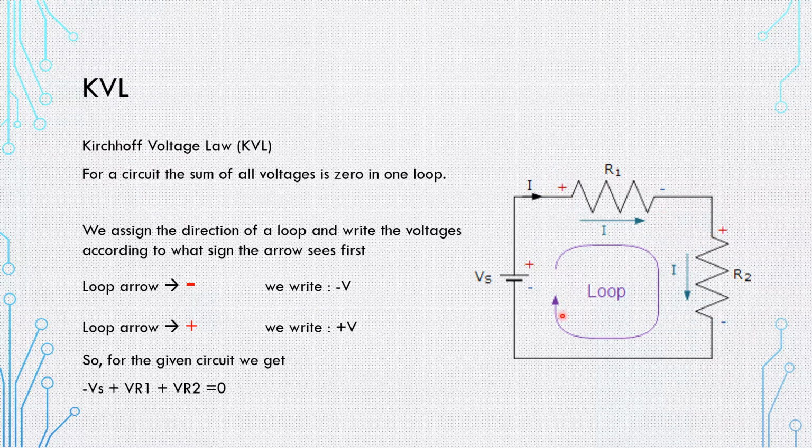The voltage will follow the current direction, or in other words, the first terminal we connect, the first sign of the resistor is going to be the same as the polarity of the voltage source you have. So you can see that at this node they are connected with the positive. So this should be the positive terminal of the voltage across this resistor, and the negative is going to be at the second terminal, the second end of the resistor.